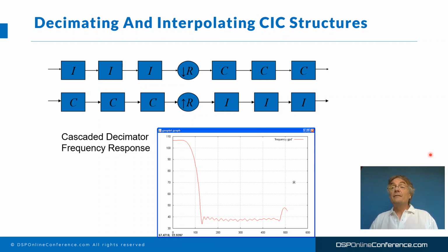Typically, having performed the first stage of high decimation filtering, we would follow that with a standard low pass filter that would do some passband gain normalization. And actually, you can see that here. We've tried to flatten the response in the passband using an FIR filter.